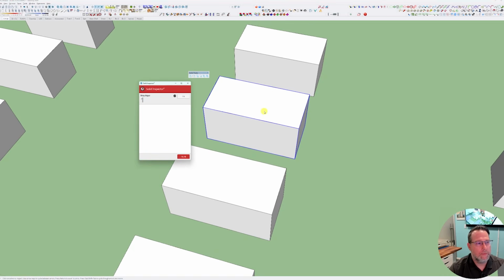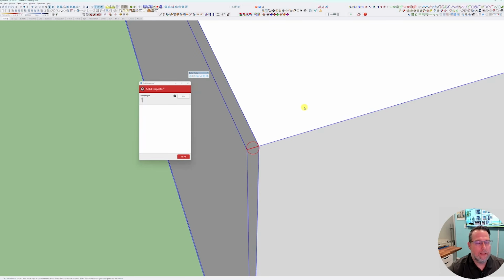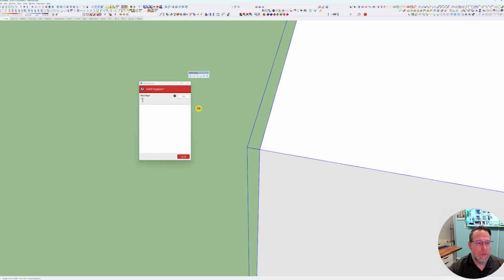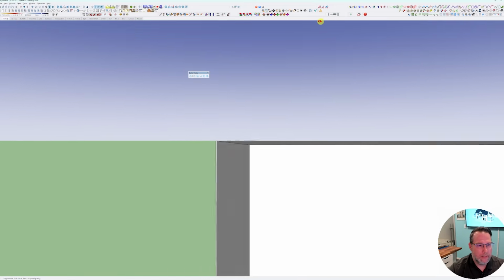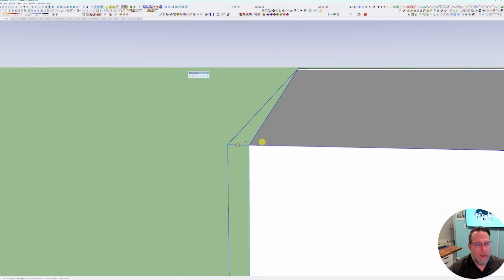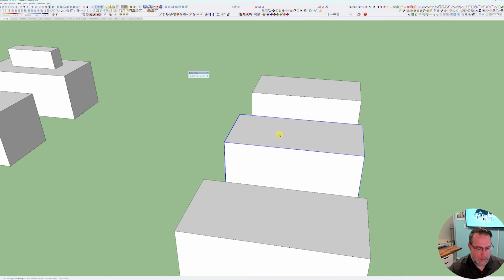Don't know why this one, hit F3, straight edge. I'm not quite sure where it is. It's not highlighting it. So I'm going to hit Tab, and Tab will actually zoom in on where an issue is. Okay, so I can quickly see I have this micro line right here, and that little line is again why this tool, Solid Inspector, is so great, because trying to find that little thing could be so tedious and near impossible. But now quickly typing F3, fix straight edge, and then now hovering over, this is now a solid.